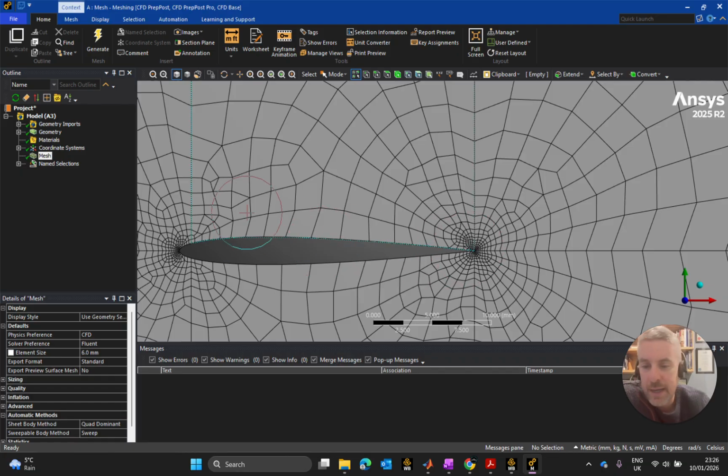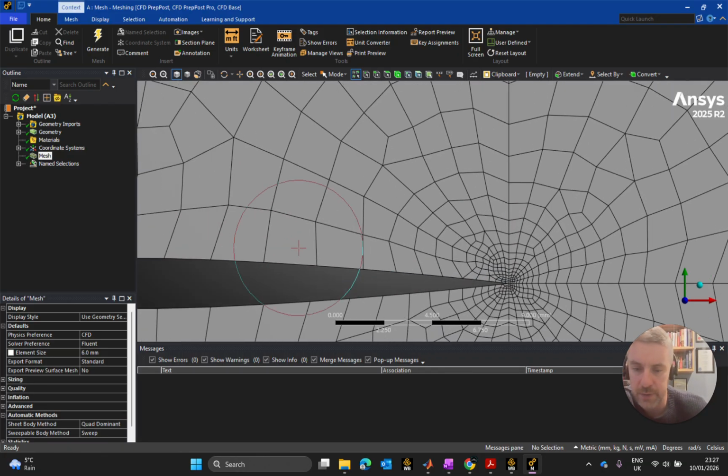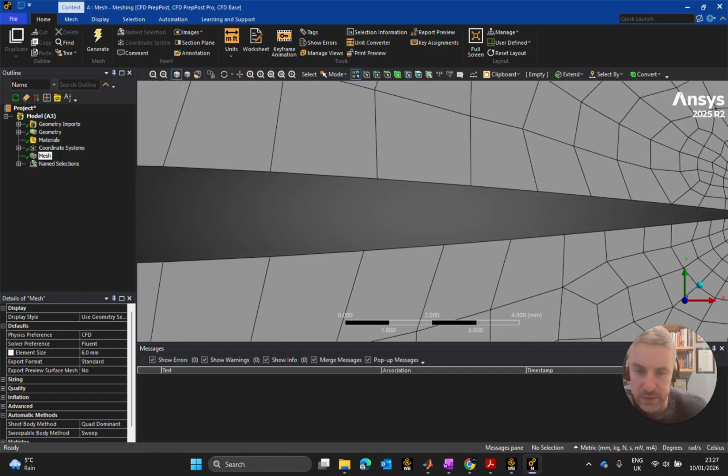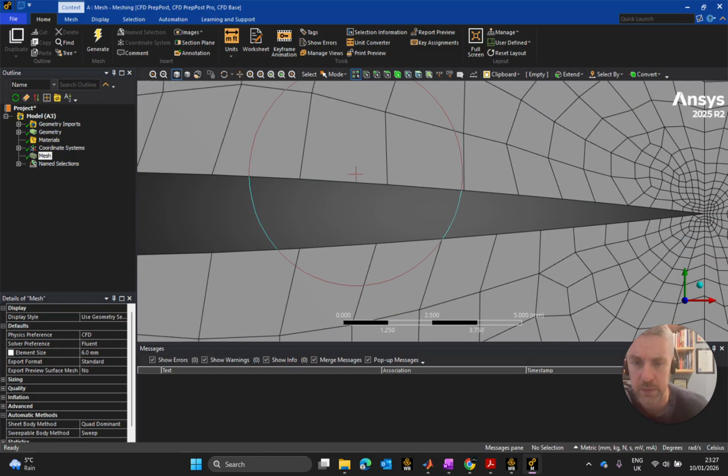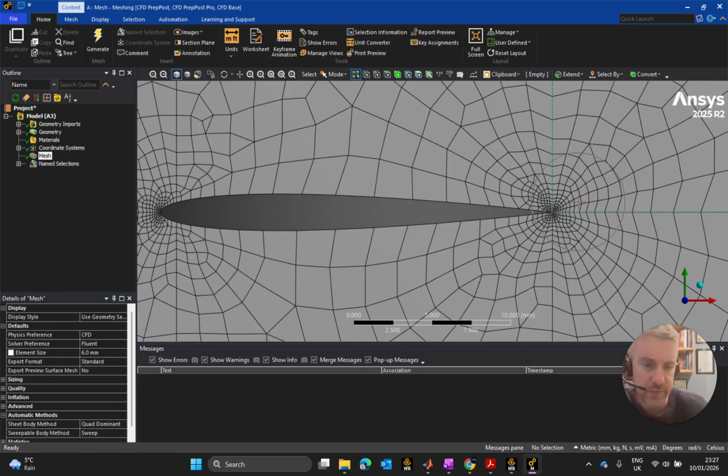At the Reynolds number, the air is like honey to this here. It is thick, and the viscous effects are noticeable in these areas at those lower Reynolds numbers. So what we need to make sure is that what happens along the wall here is very well resolved. The current mesh will in no way capture the viscous effects happening along the wall. So what you would need to do, for an unstructured mesh only, is put in an inflation layer, which is a mesh control.